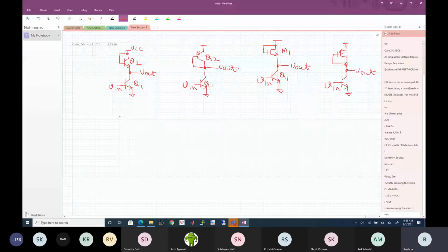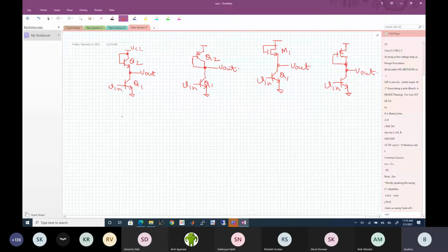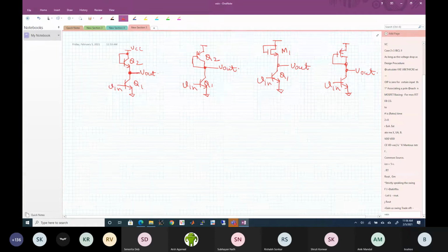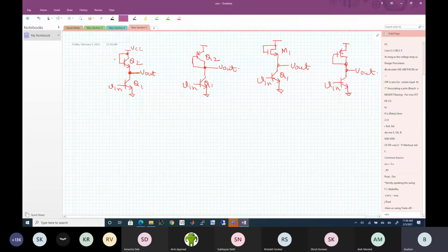This is one thing. Okay, so now what will be the maximum voltage here? It is no more dependent on this resistor. It is going to be VCC minus VBE. Correct? So the maximum voltage and the common mode voltage here is that much, because the nature of the circuit decides it.